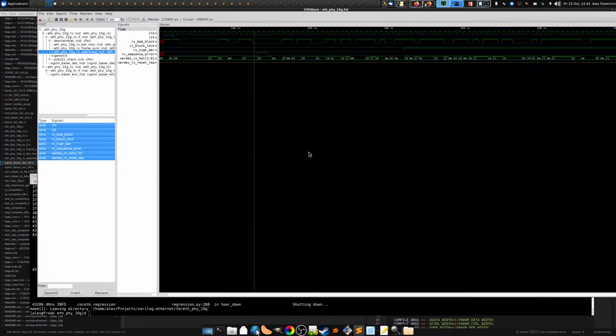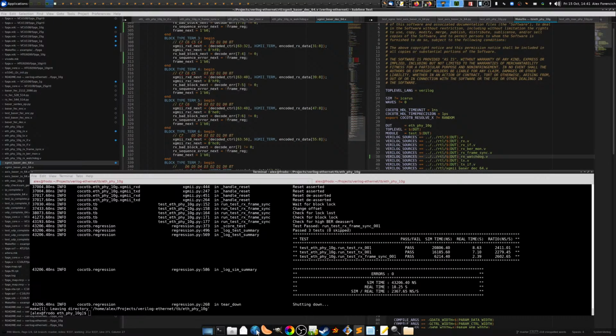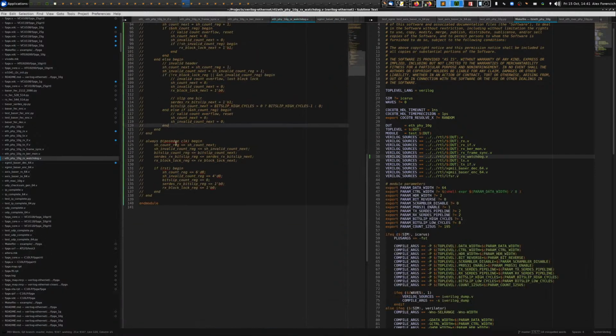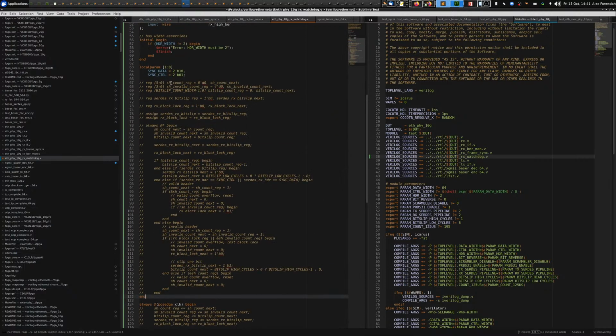All right. Perfect. Okay. Now let's actually implement all the time-based functionality here. So I'm going to need, as usual, a couple of different always blocks here. This one is for the sequential portion. This one is for the combinatorial portion.